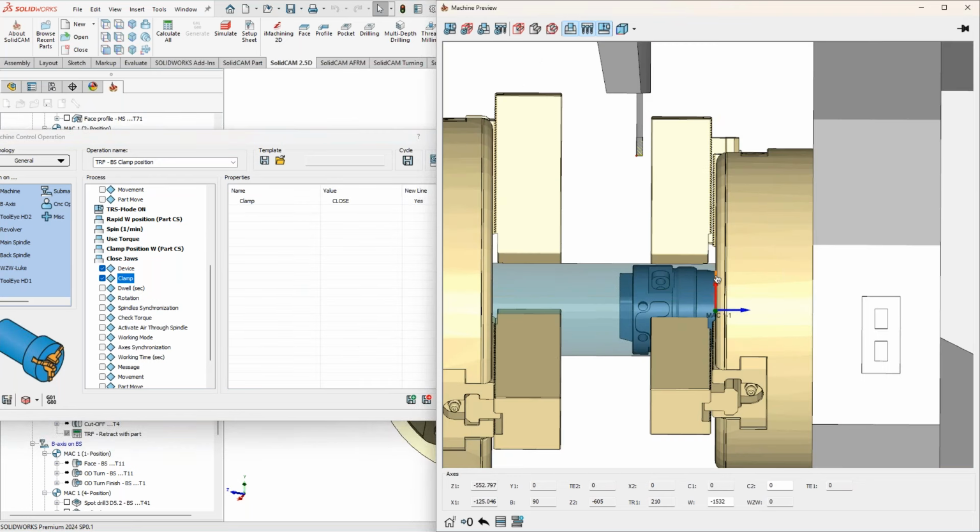Now, a very important detail. The opening values of jaws when they are open, you are defining this on toolkit level. So you go to the toolkit, you see your jaw opening position, the values that you see inside the quick axis. Any value that you put here, we are considering this as open position. Anytime when you go inside a setup and you put your closed position or where you are going to clamp the part, this is a closed position of the jaws axis.